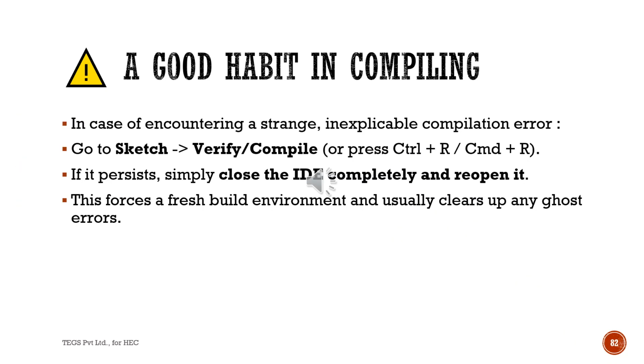A good habit in compiling. In case of encountering a strange, inexplicable compilation error, go to Sketch, Verify/Compile, or press Ctrl+R or Command+R. If it persists, simply close the IDE completely and reopen it. This forces a fresh build environment and usually clears up any ghost errors.